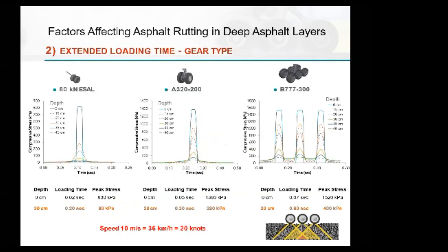And then I come to the extended loading time. We have an 80 kilonewton ESAL. It's traveling at 10 meters per second, which is like a taxiing speed. If you see here, at 0 centimeters at the surface, the load is felt for 0.02 seconds. At 30 centimeters deep, the load is felt for 0.2 seconds. Go to the extreme, Boeing 777. You have tridem axles, and look at the figure. At 0, at the surface, the load is felt for 0.07 seconds, a longer time.